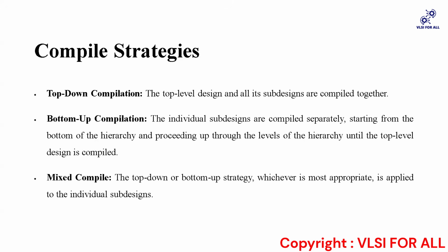So now let's see bottom up compilation. It's just the reverse version. Here the sub designs are compiled separately, starting from the bottom of the hierarchy and proceeding up through the levels of the hierarchy until the top level design is compiled. Okay, I repeat it once again. Unlike top-down compilation, in bottom-up compilation the individual sub-designs are compiled separately, starting from the bottom of the hierarchy and proceeding up through the levels of the hierarchy until the top level design is compiled.